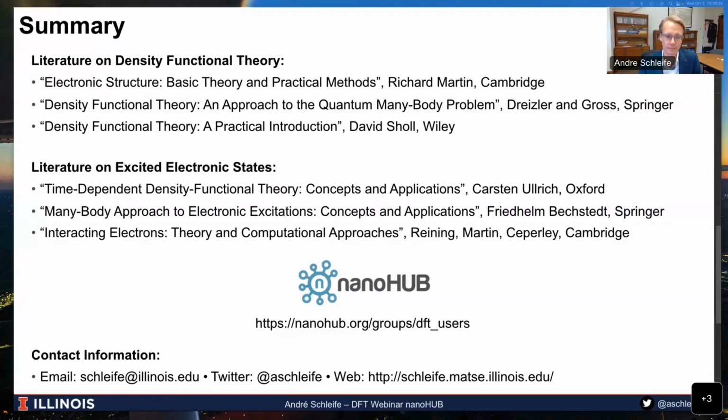All right, great, thanks. The next question, can DFT be used for dielectric simulations? So generally speaking, yes. It depends a little bit on what you mean by dielectric. And I don't want to be evasive, but there's at least the electronic dielectric properties and the lattice dielectric properties. For both, you can use DFT, right? So the electronic dielectric properties would come from essentially a band structure simulation, and then computing the dielectric tensor from that. And DFT can be used for that, absolutely.